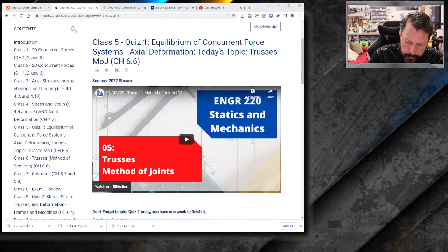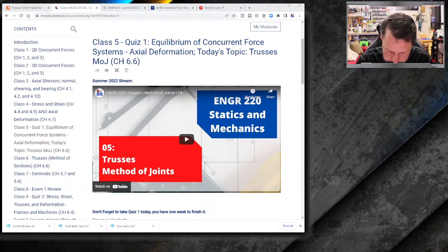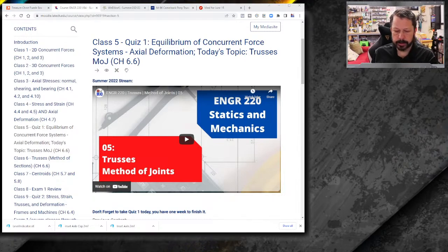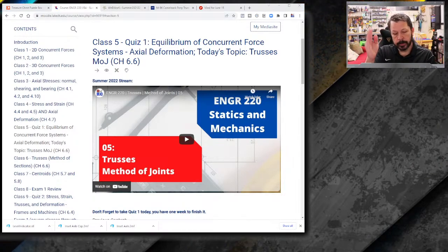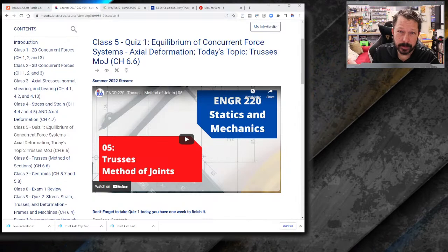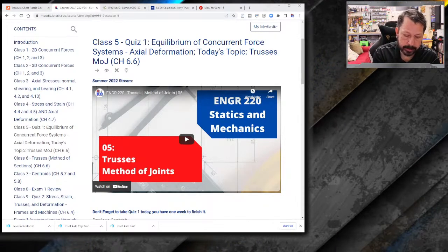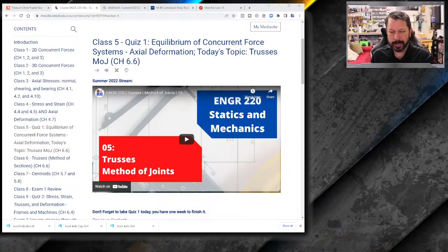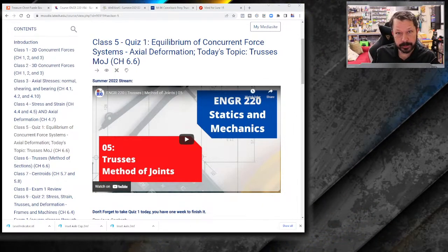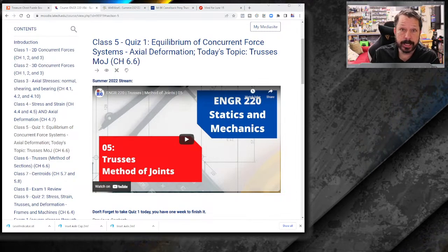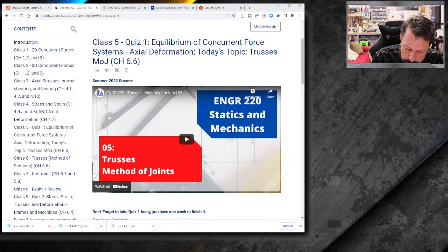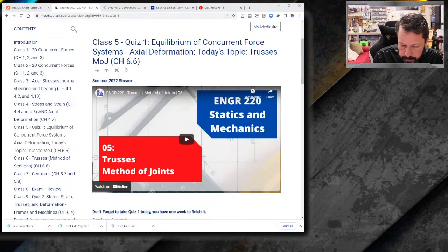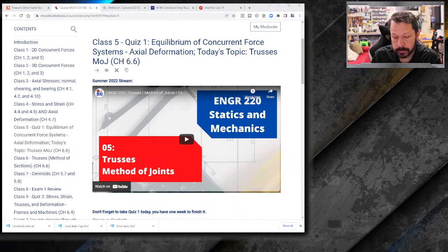And this angle right in there, that is the shear strain. How much did that previously vertical edge change? It doesn't have to start out vertical. In my example, this left edge is perpendicular to the ground beforehand, but that doesn't have to be true for it to have a shear strain. It just means that the angle changed. And this angle, we're going to call gamma, and that's going to be shear strain.